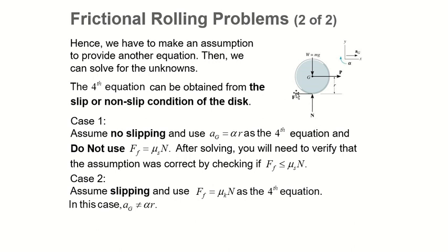Here is your normal force, your applied force, your weight, and the distance between your G and the point P. R is the distance between your force direction and the point G. So if you know I'm breaking down forces, and I have a point G and a point P somewhere in the body, I'm playing with all those distances to calculate angular acceleration and also to determine whether the applied force is bigger, smaller or equal to the frictional force.